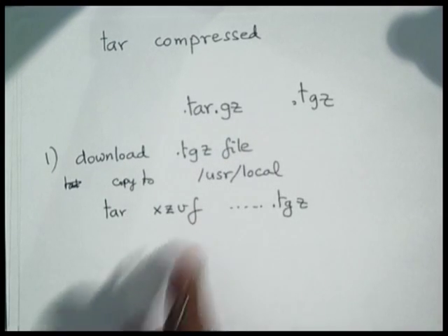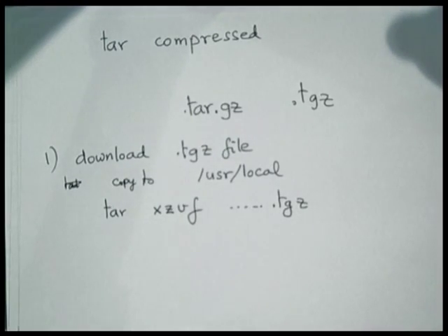If you don't use F, then it will expect a device like a tape or some external device. What it will do is create a new directory under /usr/local. Now you go to that directory. So you cd to that directory. For example, Spice may have created a directory called ngspice, which stands for new generation Spice. So you cd ngspice, or for IRSIM, you will say cd irsim.